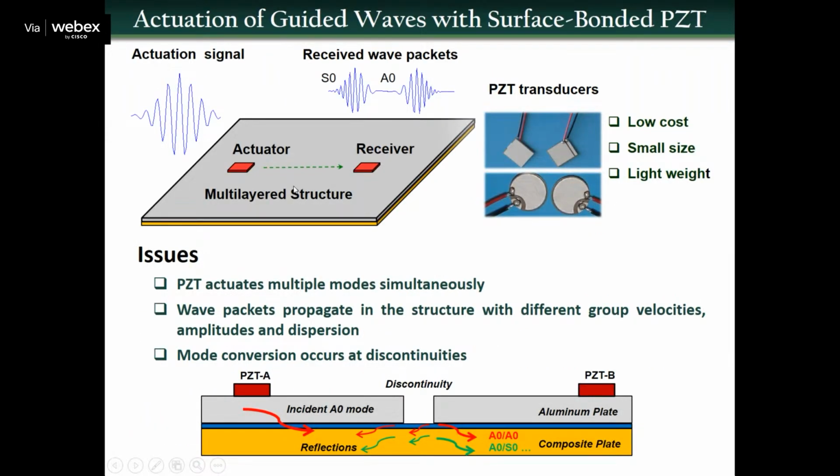Well, you can use guided wave as a monitoring technique for understanding the energy transmission between those lap joint structures. So it is a little bit more complicated than what we discussed this morning when we demonstrated the reversible adhesive bonded composite structure, RBCS.